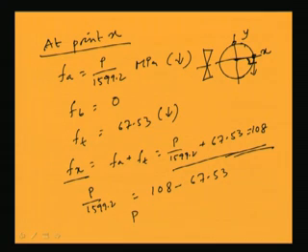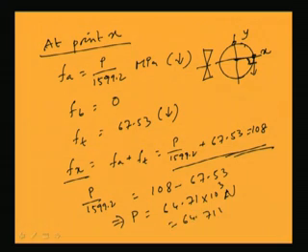So, from this I can find out the value of P. From this equation, P will become 64.71 into 10 cube Newton, that means 64.71 kilonewton. So, at point x the load which can be taken by the joint is 64.71 kilonewton. So, the permissible load is 64.71 kilonewton from the x point of view, that is, if we consider x.